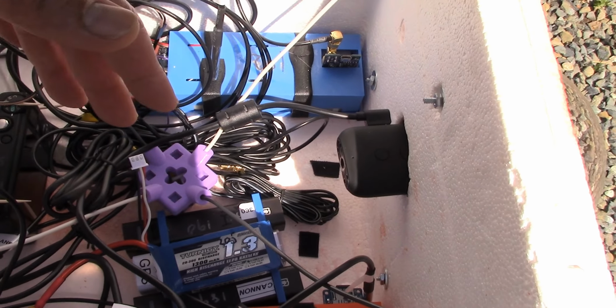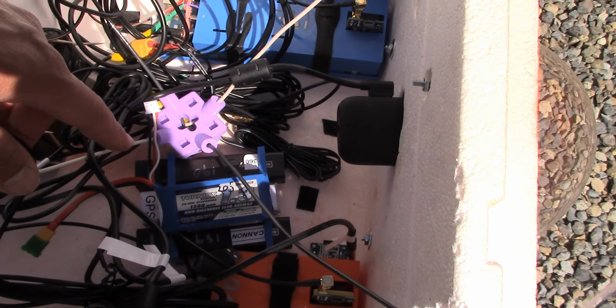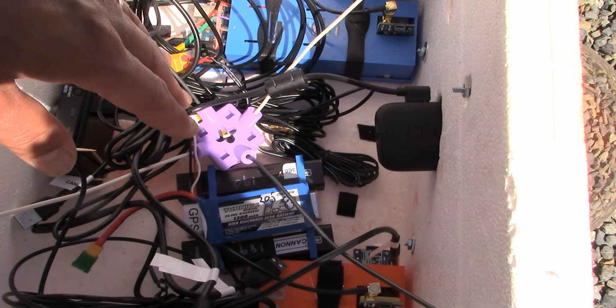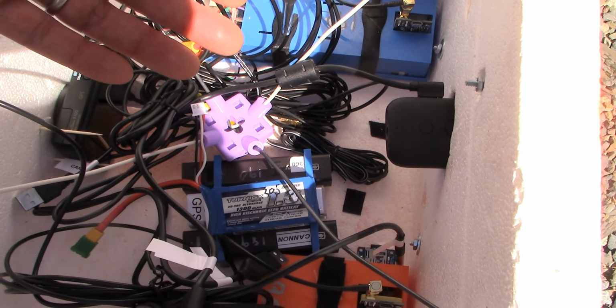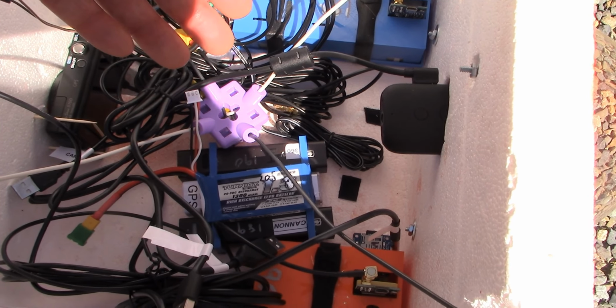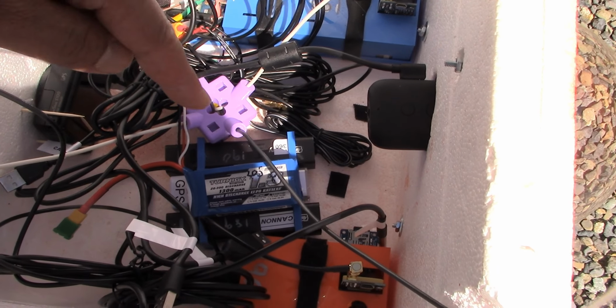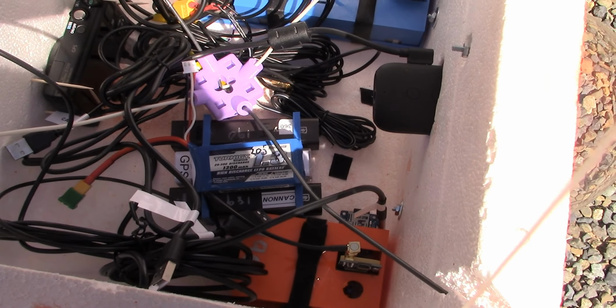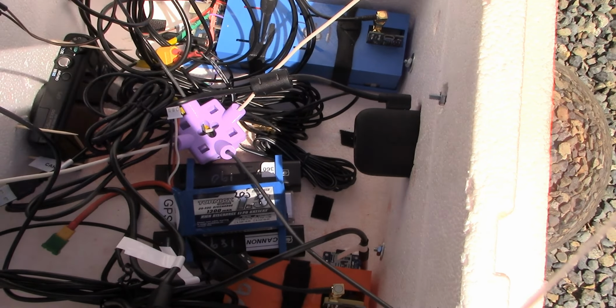So again, the power management probably could have been done better. We ran into issues where we were trying to run multiple USB sources off a single larger USB battery, and we ran into current draw issues. So that's one reason we decided to go with this redundant independent battery system. So literally one battery per system. Again, that helps with redundancy, and it also helps us with the current draw issue. So again, that's all of the batteries.